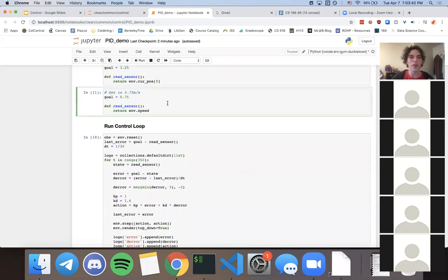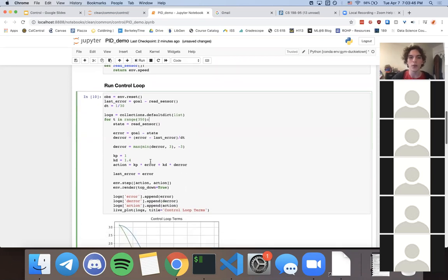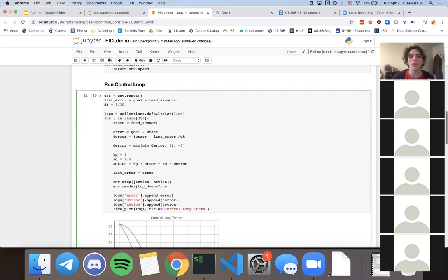So now if we try this with velocity, we can use the exact same algorithm. If our goal velocity is much higher than our current velocity, our error will be positive and we want to throttle more. The d error might still be useful. So the nice thing about this algorithm is that it's very general. It works for different systems, even though velocity operates under a different set of physics than position.